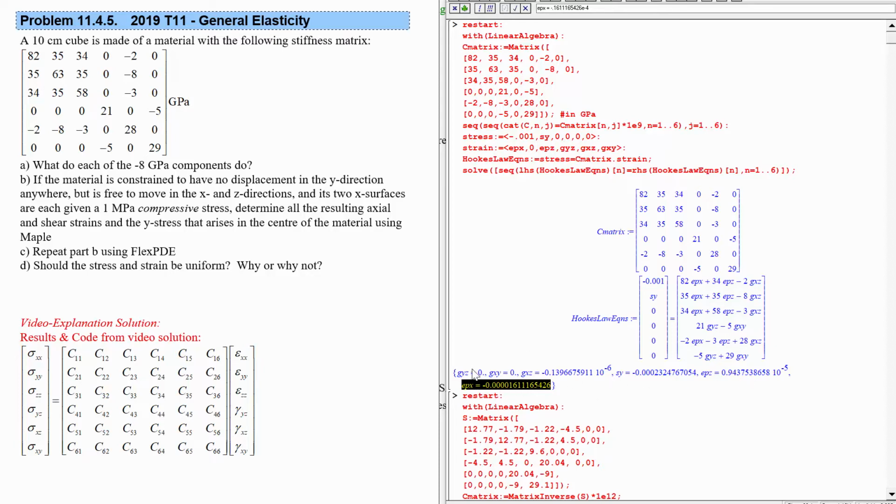The rest of this is a little bit more complicated because we fixed it in y. We have a compressive stress showing up in y as well through the Poisson's ratio, so that kind of makes sense. What about the other two? This one and this one are pretty difficult to think through. Actually, this one's not so bad. You compress it in x and it can't expand in y, so we need to put on a compressive stress in y as well, and that's where this comes from, but it can expand in z, so it gets some tensile strain in z.